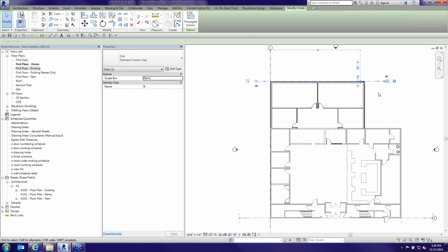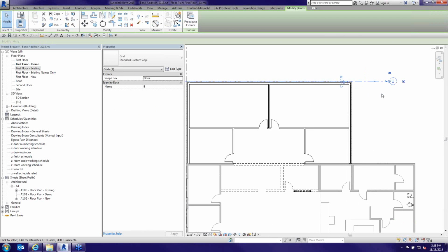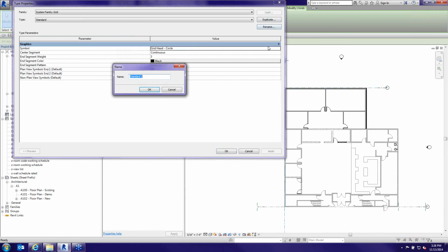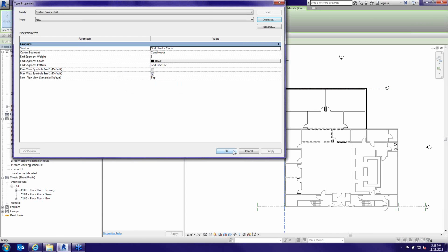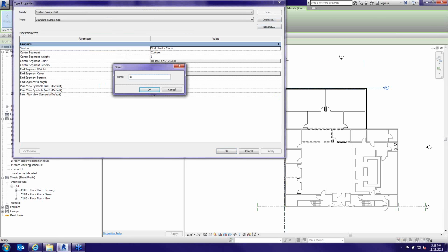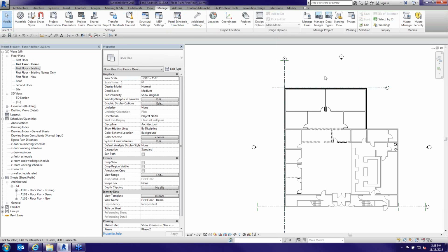So personally, there's a lot of different ways to do this. You can create different grid types. I personally create grid types in a filter. So for me, I usually in Revit go edit the type, duplicate it. I have one called grid new. I'll take this one, edit the type, duplicate it, and call it existing. Or I did these backwards, but you'll get the point. Probably spelled that wrong too. So I personally go in and create different grid types, and then I use filters to filter those out. So that's kind of one of those things when you get into it. These are not phase dependent.